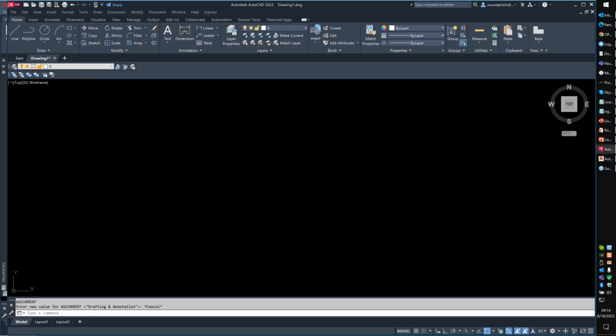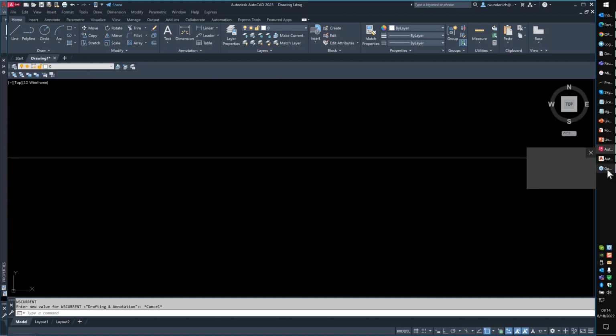The other reason is how you're loading your profile or how you're launching. If you're launching from the icon, usually it works. If you're double clicking on a DWG, you may not be set to be grabbing the correct AutoCAD. And so it may not know which profile or workspace you're on. That's more of a technical side that we would have to address. Any other questions on this?